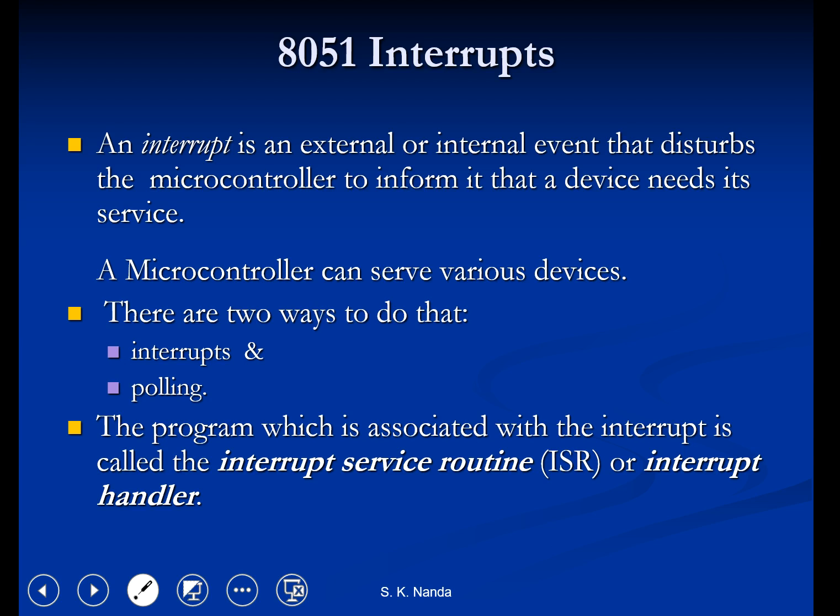It entirely differs from the polling method wherein the processor must check sequentially each device and ask whether the service is required or not while consuming more processor time. Interrupts are the events that temporarily suspend the main program, pass the control to external sources and execute their task. It then passes the control to the main program where it had left off.